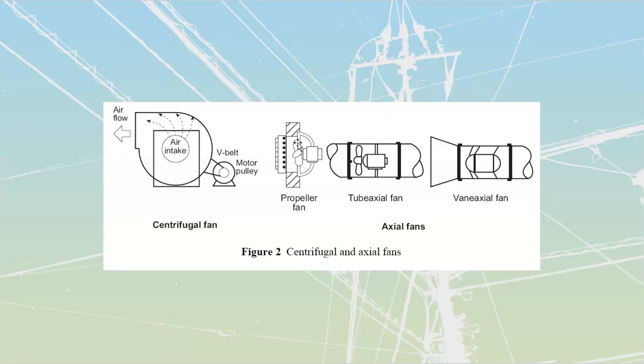Static pressure varies with the square of the fan speed. So if you double the fan speed, you get 4 times the static pressure. So fan speed doubles, 2x speed equals 2 squared times the static pressure that I'm going to have. Static pressure is just the relationship between the pressure inside of something to the pressure outside of that. If you overpressurize your ducts, you end up with rupturing.